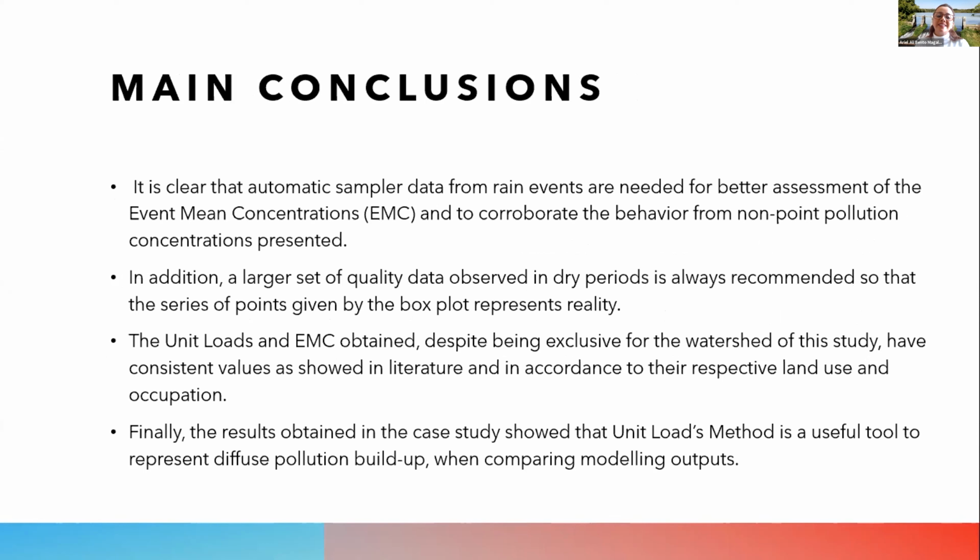To conclude, it is clear that automatic sampler data from rain events are needed for a better assessment of the event mean concentration and to corroborate the behavior of the non-point pollution concentrations presented. In addition, a larger set of quality data observed in dry periods is always recommended, so that the series of points given by the box plot represents reality. The unit loads and the EMC obtained, despite being exclusive to the watershed of the study, have values consistent with the literature in accordance with their respective land use and occupation. Finally, the results obtained in this case study showed that the unit loads method is a useful tool to represent diffuse pollution buildup when compared to modeling outputs.